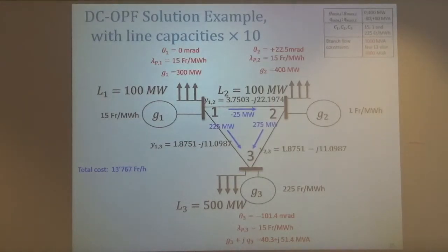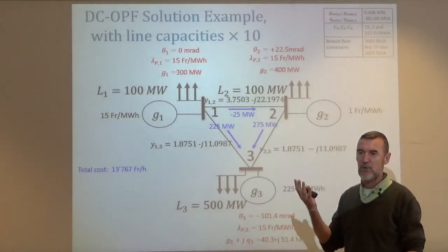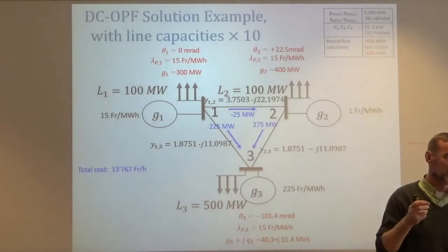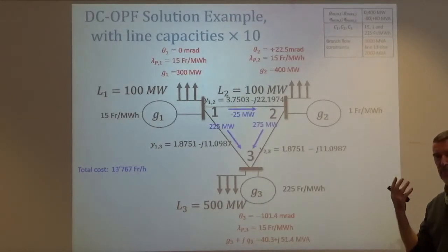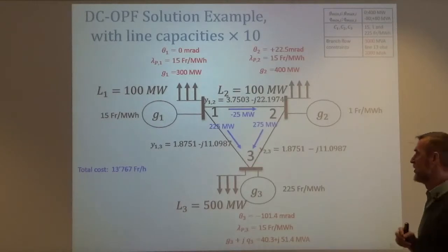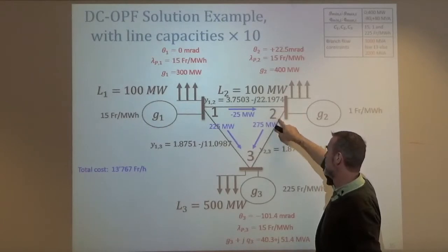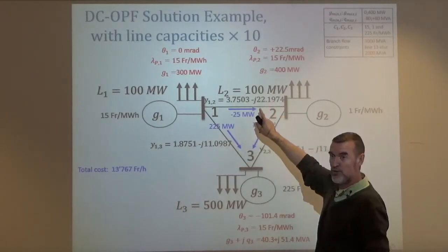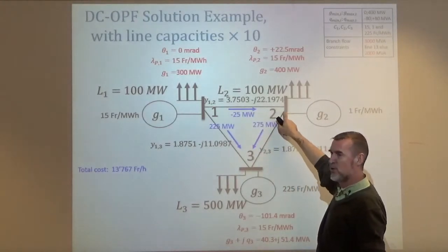If I had a graph theoretic problem, well, if I would be able in electrical grids to route the power... Some people have proposed to make power routers. And we have power routers when we have converters, if we have direct current lines that are transformed. So if this would be DC and we want to have the flow going here, so true DC, not DC approximation of the AC problem, then we could have what is called power routers.